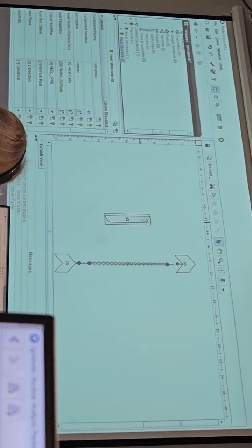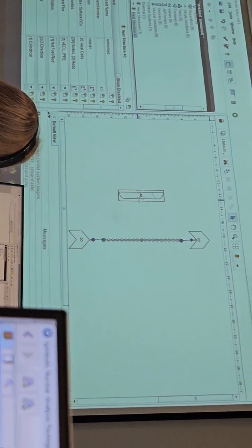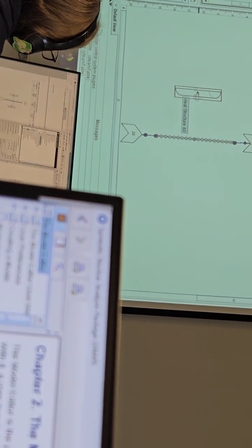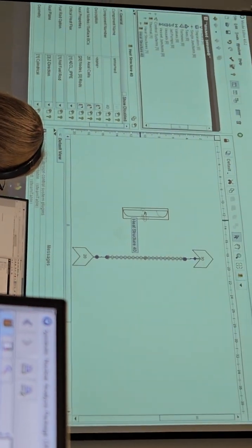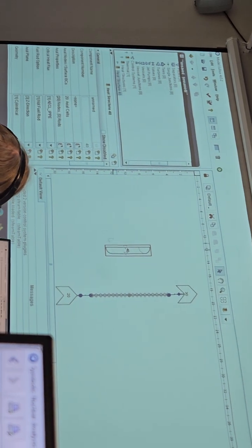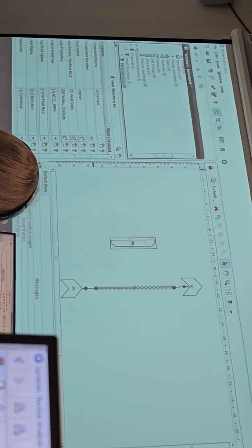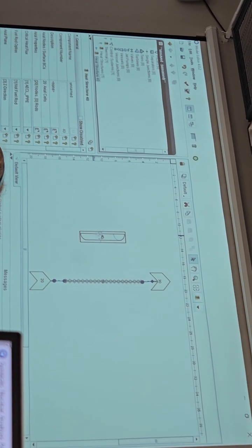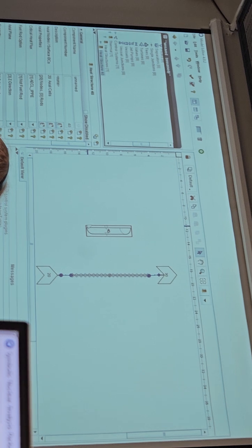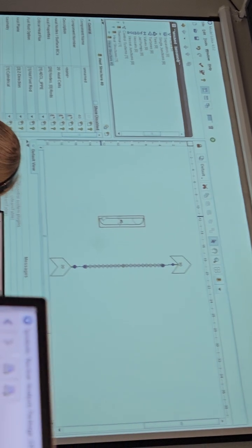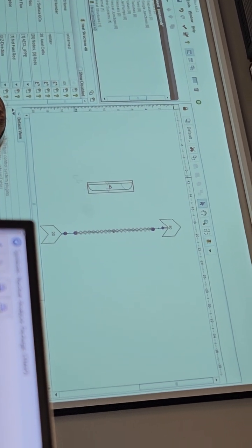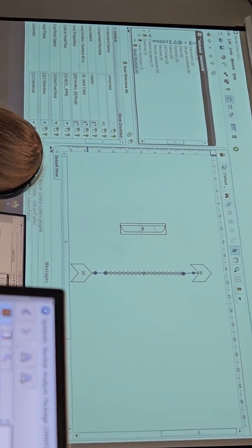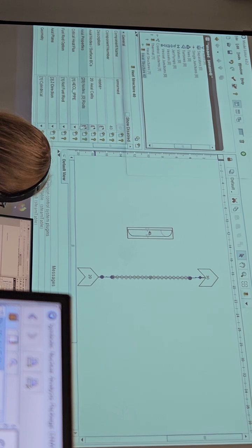Yeah, here is the heat structure. On your monitor it is probably a red color. Here it is a white one. Doesn't matter actually. For this heat structure, we just need to renodalize it the same way as we did for the pipe. Now it is a 20 cell heat structure, but the nodalization is uniform, cell by cell. We need to go to axial properties.